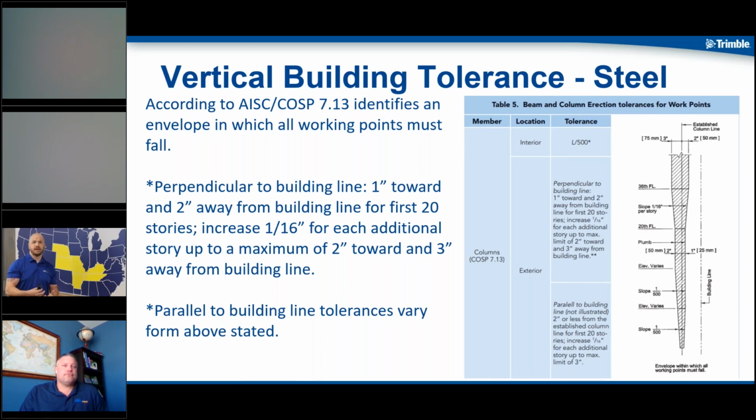So when we talk about building control points and civil control points, what we're trying to elaborate on is that it's always important to have building control points at every level as you're working up. Instead of building an 8-story building and pushing somebody down to a civil control point down on the site, it's best to also have building control points. I'm not saying that the civil control points are off, but it's also a very extreme requirement, if you will, to have building control points inside of that too.